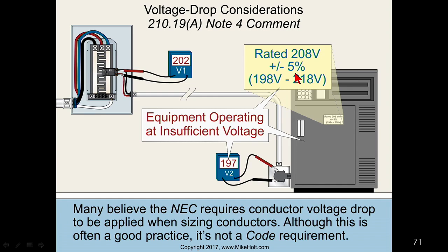I'm saying I'm going to make an example that I would rather it be 240 volt systems. What is the rating of the equipment? 230. Right, 230. The equipment rating is not the same thing as the nominal rating of the system. So this would be a 230 volt rated piece of equipment. 90% of 230 is 207.